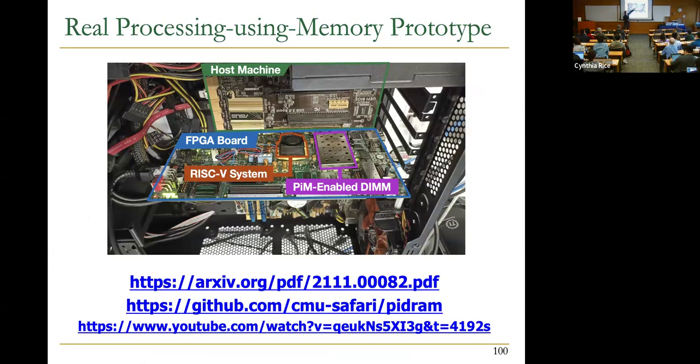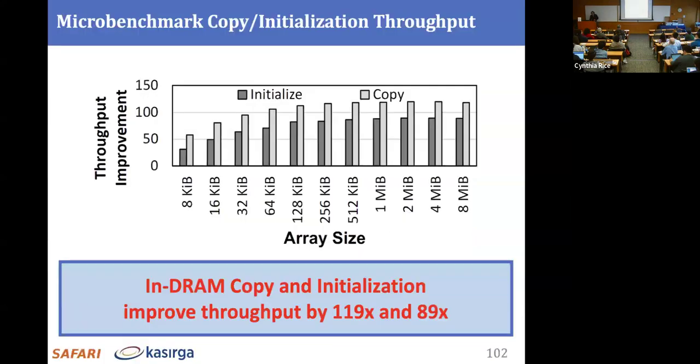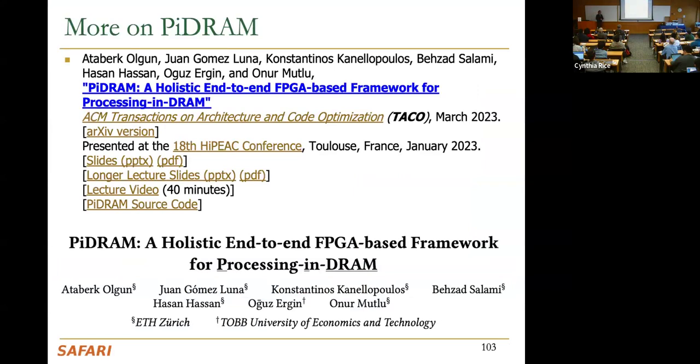We also do true random number generation. So if you get a rand call, it gets offloaded to the memory controller. So you can actually test things end to end. If you're interested, you can take a look. And we see significant benefits because the RISC-V processor is pretty wimpy in this particular case. So you can actually do real testing with this sort of thing with real DRAM. And I think that's fascinating, because it shows that real DRAM chips are actually capable of this, even though they're not designed for it. You can get this operation very reliably.